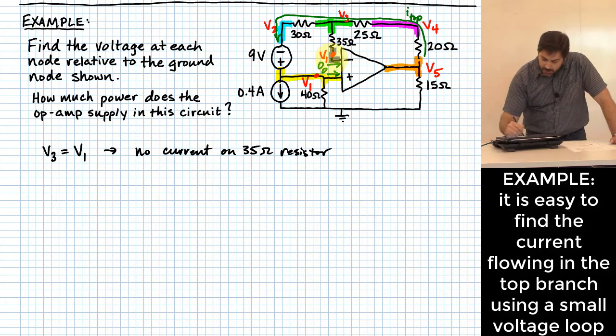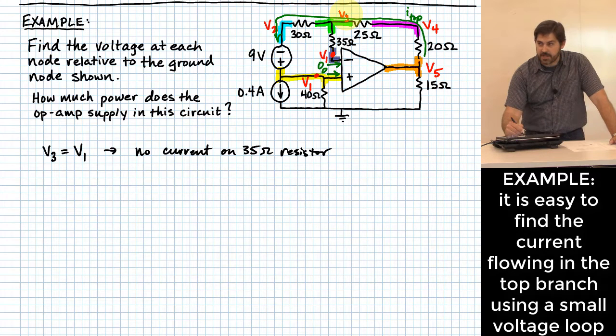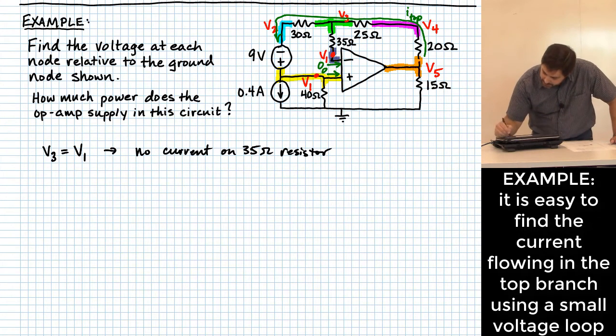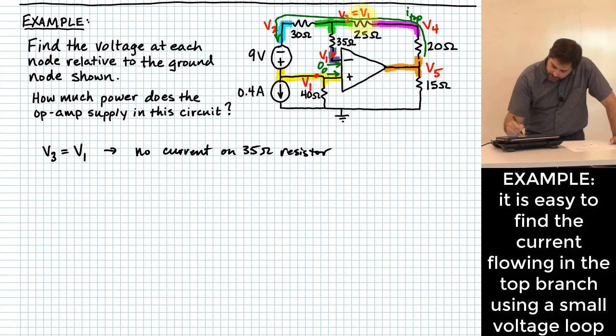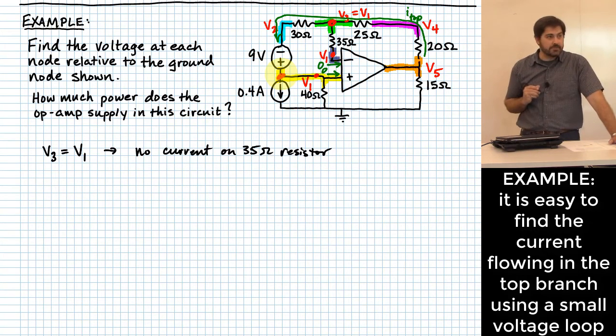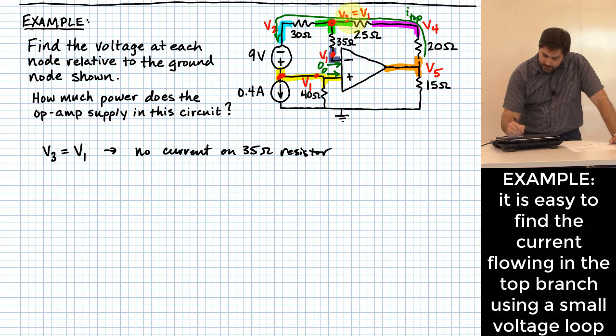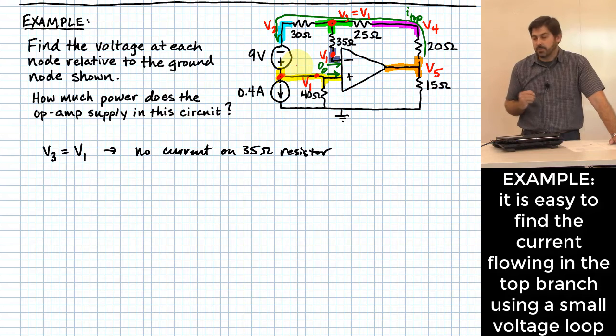One of which is, we just said V1 is equal to V3, right? Did we say that? That means I can say V3 up here is equal to V1. How much voltage do I have from that location right there to this location right here? Tricky question. How much voltage, if I was to put my multimeter on those two big red dots? You'd have zero voltage. Why? They're at the same voltage, right?